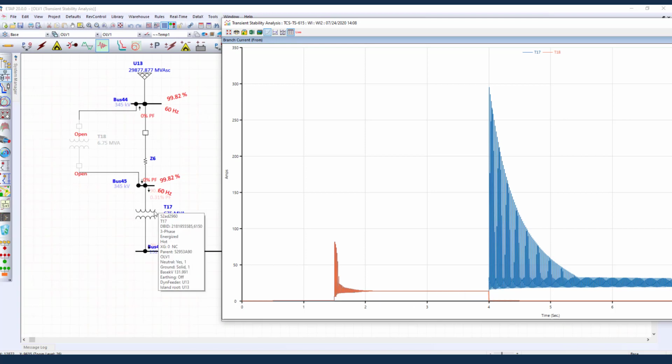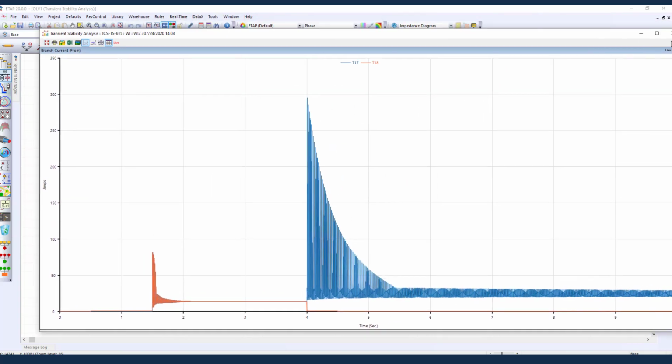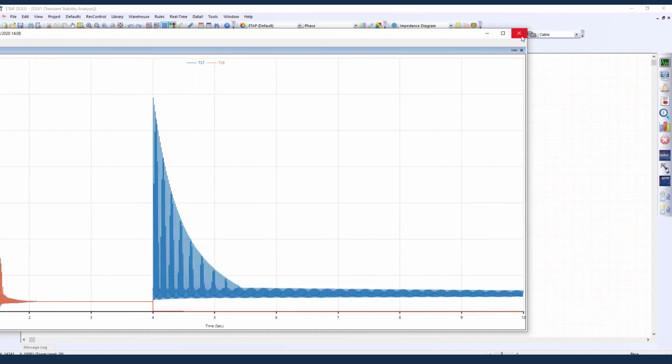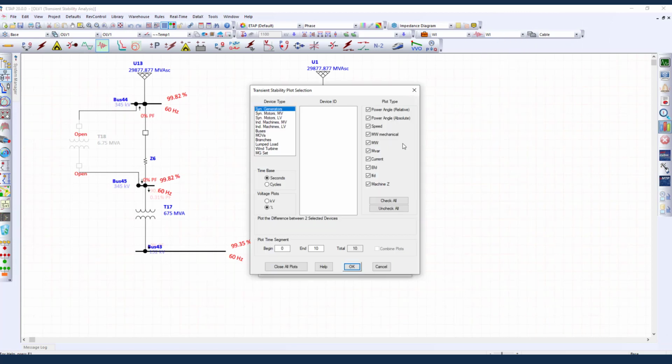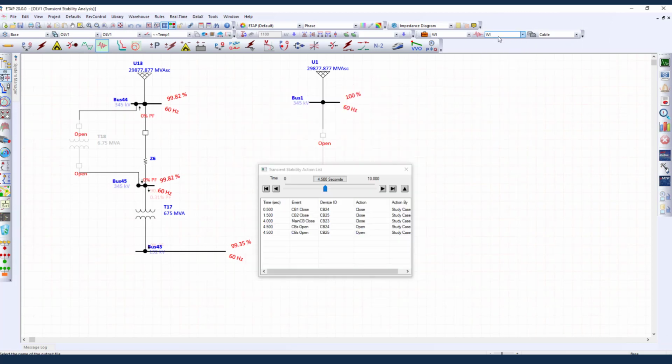So it's going to limit the amount of current that can go into this transformer. So the second transformer, when it gets energized, is going to have much lower inrush in this case. As you see here, this case has 300 ampere versus the last time that we did this. Actually, if I go to the